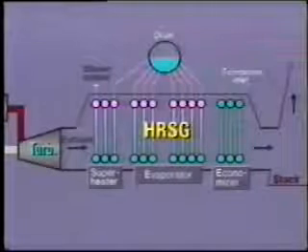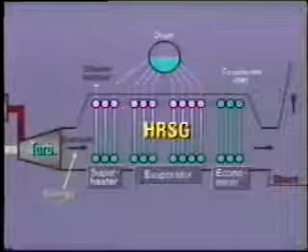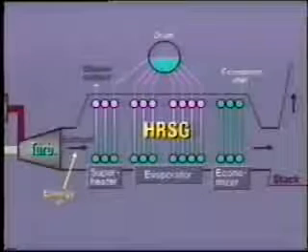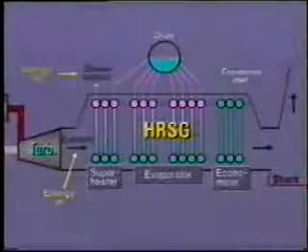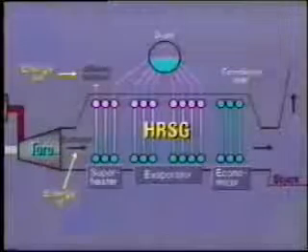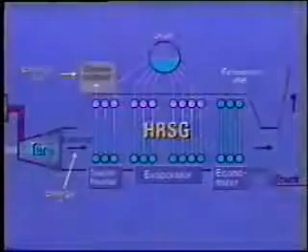But what could make the steam pressure rise and cause the safety valves to open? Well, steam pressure is actually controlled by a balance of two functions. The amount of energy extracted by the HRSG from the exhaust gas, that is, energy in. The amount of steam energy being extracted from the HRSG, that is, energy out. In normal operation, the two work in equilibrium. Energy in equals energy out. The steam turbine plus any other process steam demand absorbs all of the steam energy being produced by the HRSG.